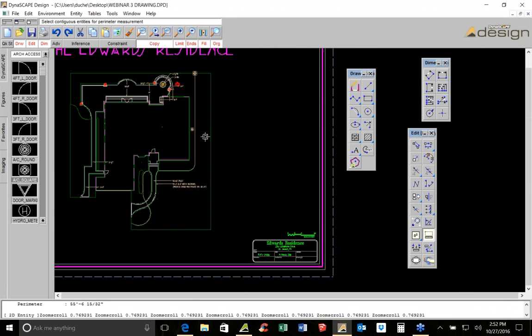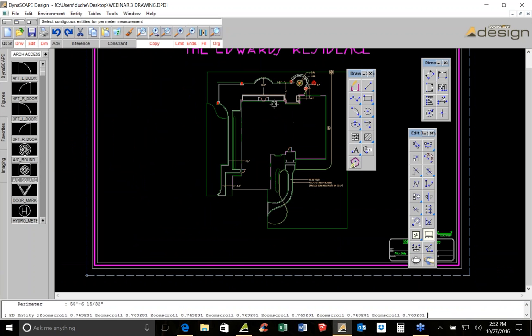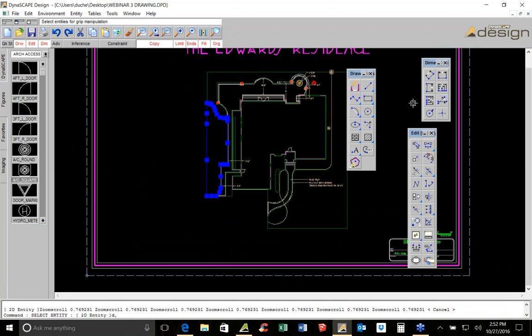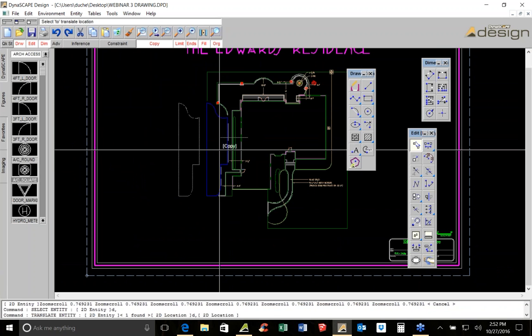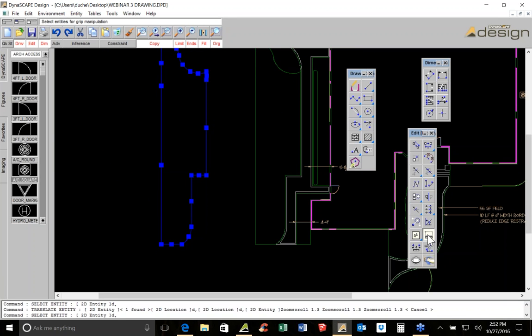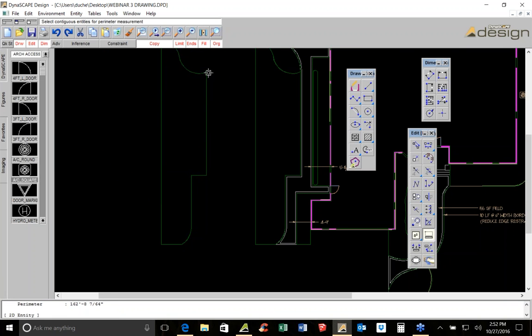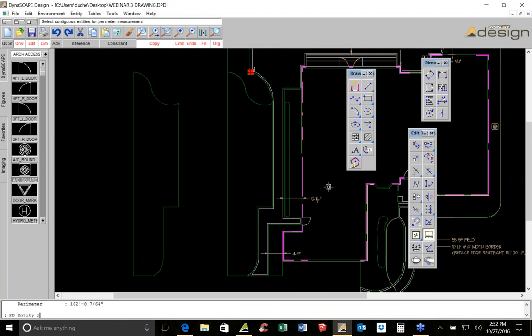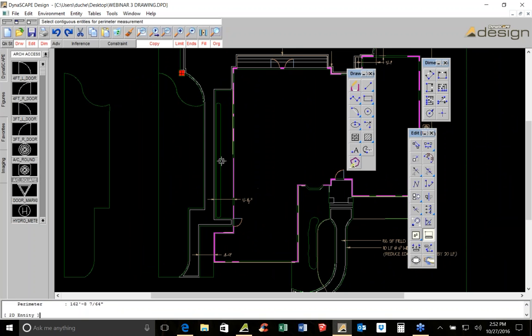How about if we have a courtyard or something like that where, let's just say they wanted this enclosed with brick. Just click that line, hit the measure the line tool, and we need 162 linear feet. Okay? Perfect. Thank you.